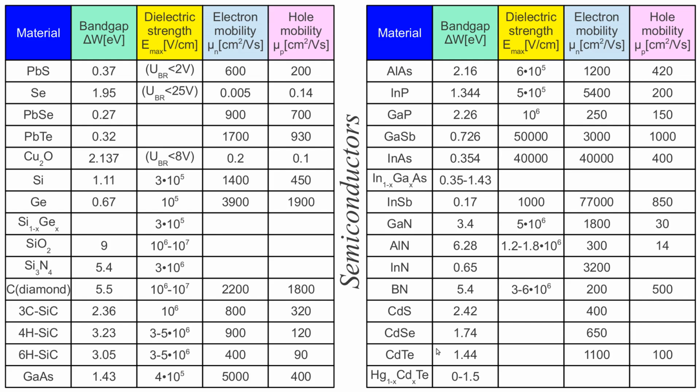Finally, if we need photodiodes for very long wavelengths, like thermal radiation, 10 micrometers, then mercury cadmium telluride is a semiconductor of choice. Of course, to make it useful in the very long wave infrared region, we have to cool this detector down to cryogenic temperatures.